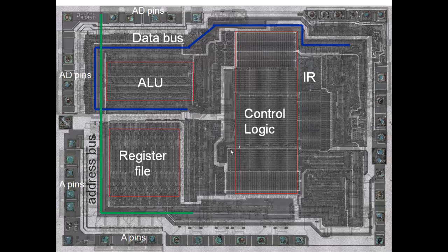And you can see why, for example, I don't have the exact area of this particular one, but you can see all the pins are distributed all along. So if you use a separate memory bus and a separate data bus, the separate address would have required 16 pins and 8 pins would have gone to data. So 16 and 8, 24 pins would have gone just there. And so, if you have a 40-pin package, you have very few pins remaining for the rest of the tasks. So it's for that reason that the address and the data bus have been multiplexed.